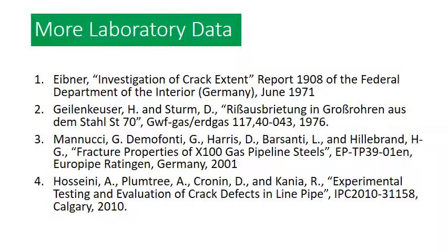I don't think that those are suitable to be put into a pipeline model. You're going to have different work hardening properties, different behavior potentially, and I've seen in some other work that those data points come out as overly conservative, and I don't want overly conservative data points to be pulling my model in the wrong direction. I don't think that's appropriate for the overall reliability of pipelines.